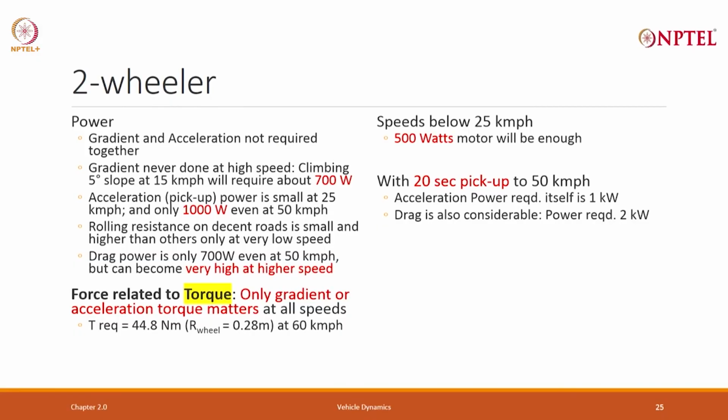But if I go to 50 kilometer per hour, the situation changes. At 50 kilometer per hour, the acceleration alone is 1 kilowatt, and drag and other things are also considerable. So, you will require about 2 kilowatt.